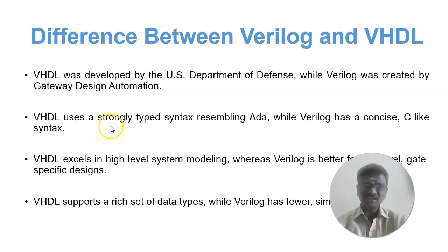And VHDL uses a strongly typed syntax. Okay, so it is similar to the Ada language, but Verilog is similar to our C language. That's why we are going to see Verilog, because its syntax is similar to that of the C language. Then VHDL is used for high level system modeling, but Verilog is used for low level and gate level system designs, right? So this is why we are going with Verilog rather than VHDL.